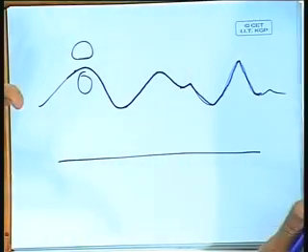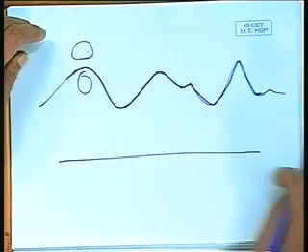It's the wind that keeps them moving up and down. Otherwise, under normal condition, there will be a total straight line. Yes, if it is a straight line, there is no wind, pressure is the same. Pressure is atmospheric. So physically we can make out that sound, but this one is changing and has to have the same pressure. On the free surface, it must be constant pressure. This is simply one of the conditions imposed on any flow, that the pressure on the free surface, otherwise it will not remain free, it is constrained, it is a free surface.